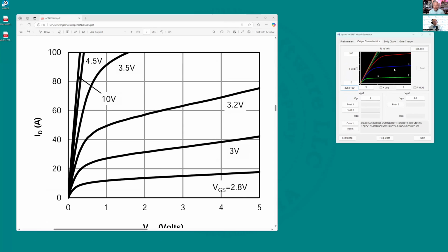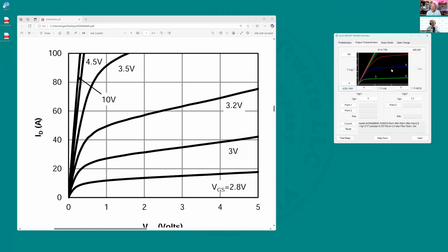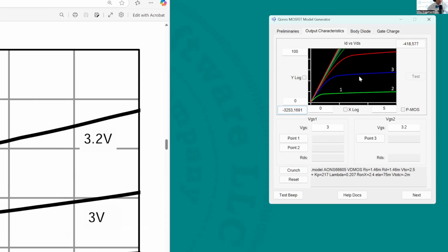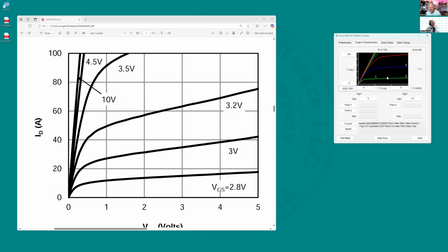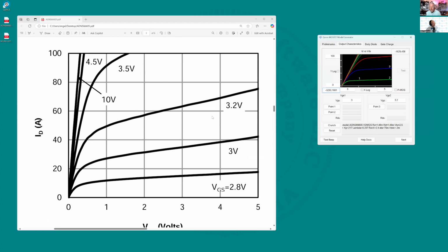And the reason for that is kind of a Windows security thing. One application cannot change the cursor in another application. But if you mouse down someplace, then that application has locked the cursor. It owns the cursor. So I come back, I need to digitize this point. So I come back here, mouse down, I got my cursor, I point at this corner, and there it is. So this tool now knows exactly how to read out any point here to the voltage and current.